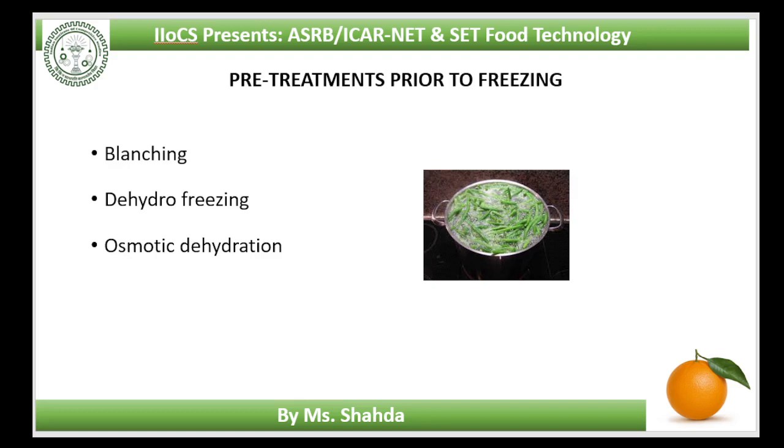However, there are certain disadvantages associated with such drying. Free flow of the product is hindered due to particle agglomeration. Color is affected. For example, kiwi and strawberry fruits are susceptible to heat modification. For such fruits, air drying must be replaced by osmotic dehydration, which is more effective even at room temperature and which operates away from oxygen.